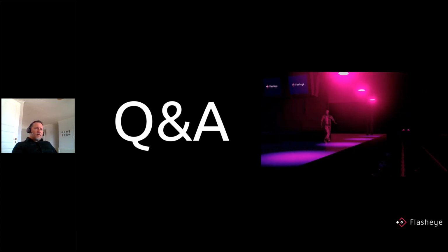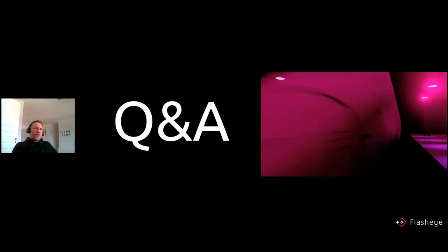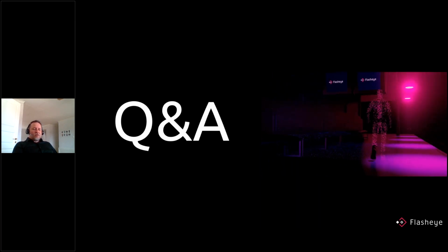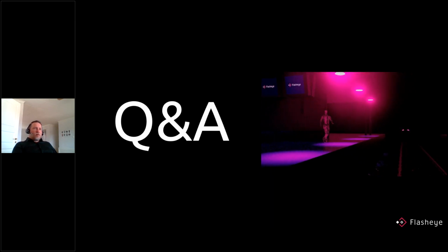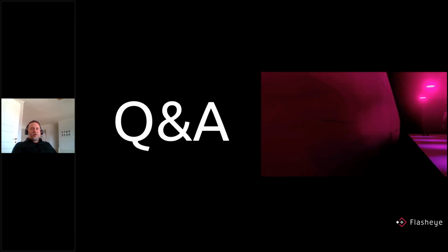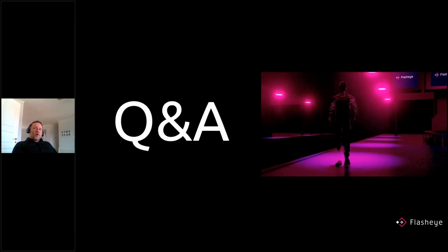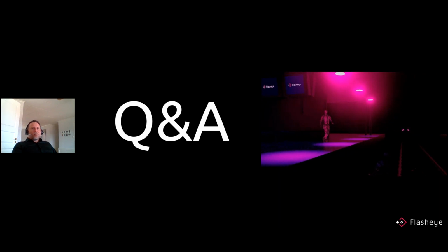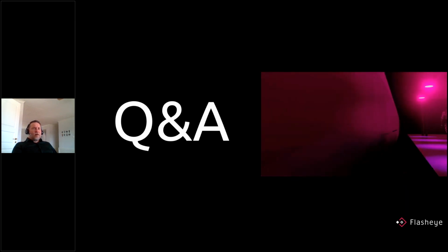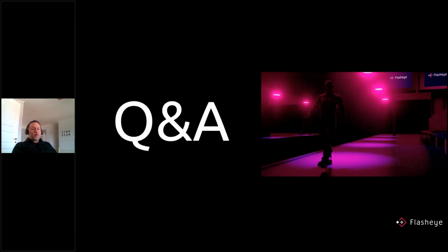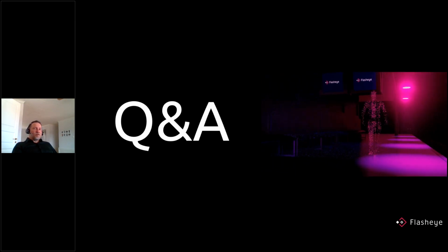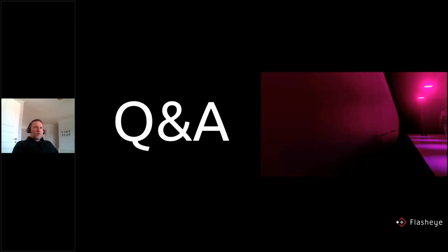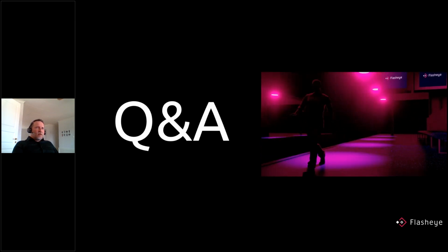Another question: would a LiDAR setup need a lot of power for remote deployments? No. We can run on small industrial computers, fanless. So if you deploy such a computer with a LiDAR, we are about 60 to 80 watts, I would say. So our solution with our chosen LiDAR sensor is very, very energy effective for remote installations. You can run on solar power, fuel cells, etc.